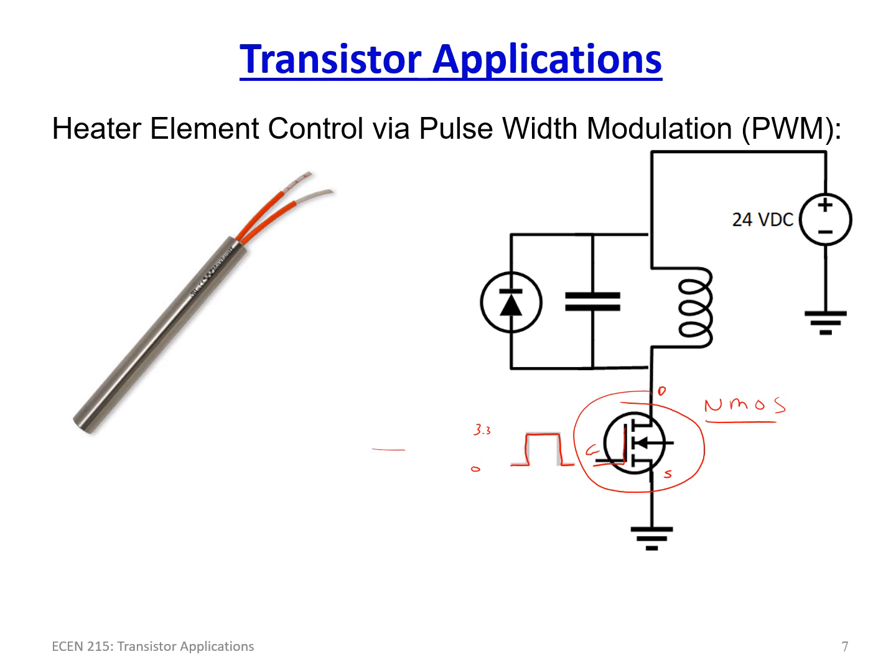Now, where this signal comes from typically is a microcontroller, an MCU, and we're going to be talking about that in the next set of topics. But with a microcontroller, say like a Raspberry Pi or an Arduino that you can purchase and program pretty quick and easy, you can generate this signal coming right out of, say, port 1.0 of the processor on the little header. You literally have ground, and you connect the ground here to the ground pin here, and then you take this signal and you literally tie it to the gate pin of this, and you can actually turn on and off this heater.